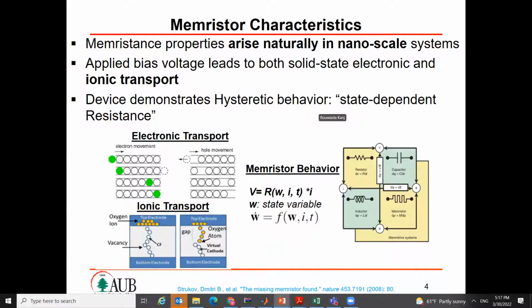Okay. Now what happens is that they found, if we have an insulator material that is not supposed to pass current, and it has a top electrode and a bottom electrode, if they somehow stress it or apply some high voltage, or what they call burn in, they will create some form of a filament, and this filament can create a resistive path.